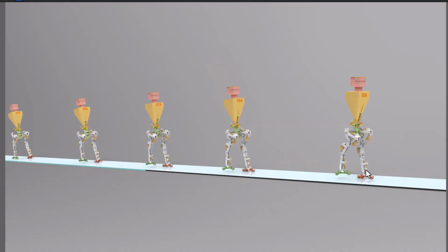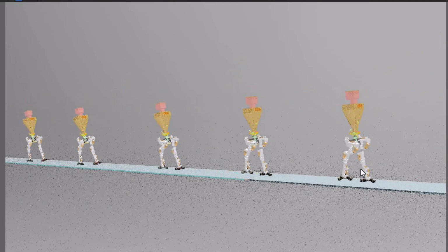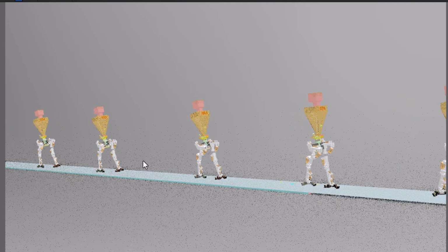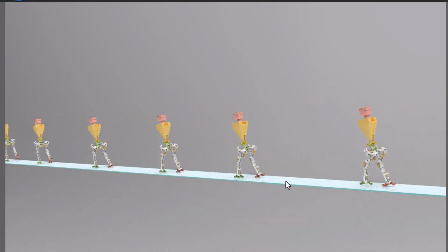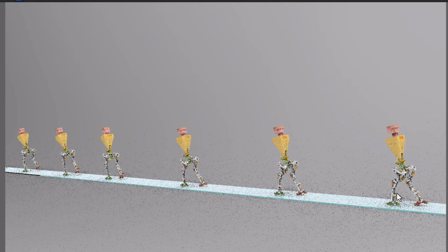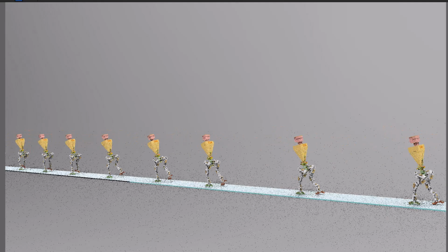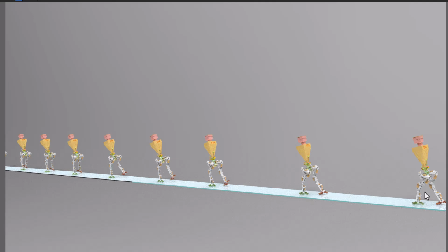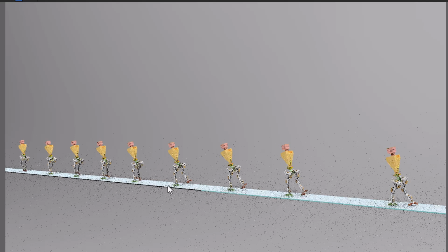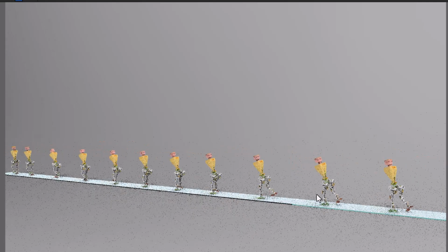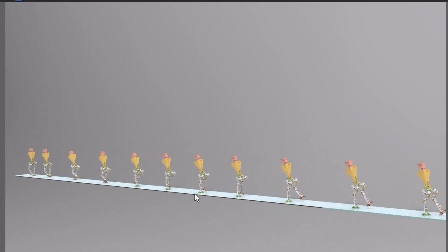And I wanted to do just a little bit of some analytical work. We have the leg that is free, and that's a very important leg, and a very important foot. You can see as the robot walks along, the right foot is converted into the foot that is free, and the left foot is converted into the foot that's on the ground. And once the right foot is free, then you can see that the right foot can be swung forward.